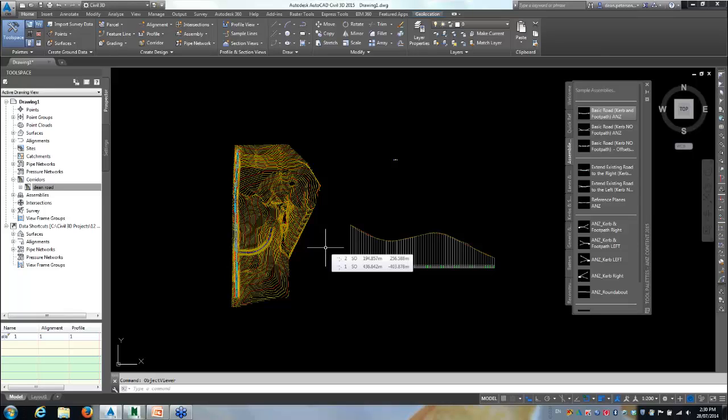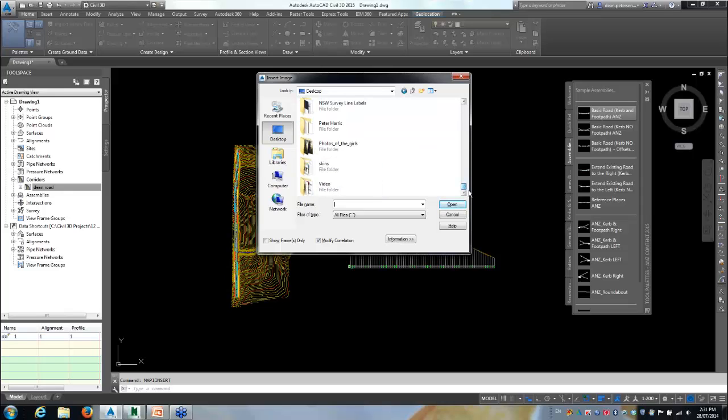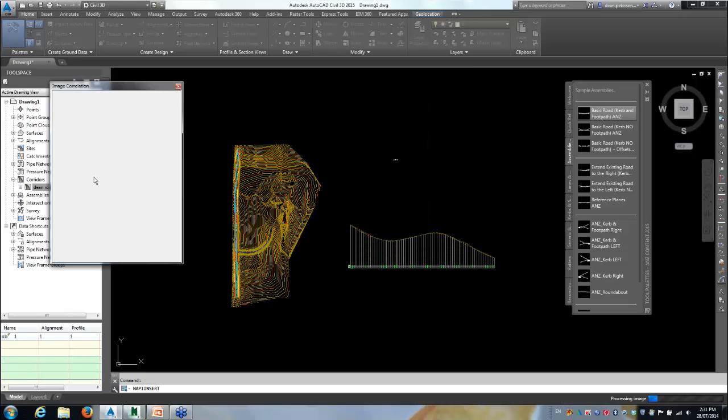However, the next step, before we do that, we didn't bring the aerial photograph. So the same aerial photograph we used in InfraWorks, we can use in here as well. For those who don't know it, there's a map insert command. And we can just read exactly the same image that we were looking at before. If I can just find the right folder, here it is, in InfraWorks. Map insert being a map command, it will